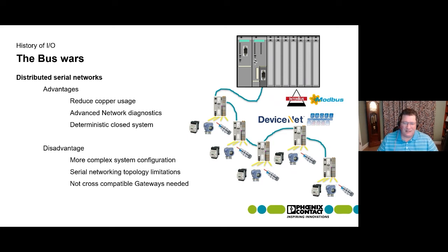This was key because I need to, as a programmer, know that I'm getting my data in a timely manner every single time because my program counts on it. When I see a sensor turn on, I turn something off. If a sensor turns on, and it takes me 10 milliseconds to get that data, 100 milliseconds to process that data, another 10 milliseconds to turn the output, I know I have a 120 millisecond cycle in that. Now, if